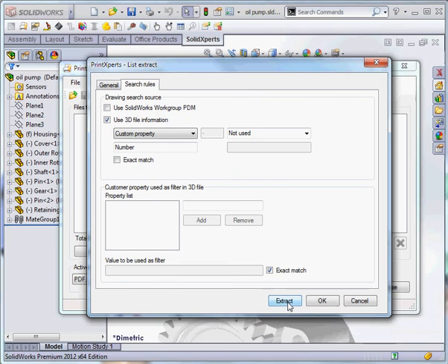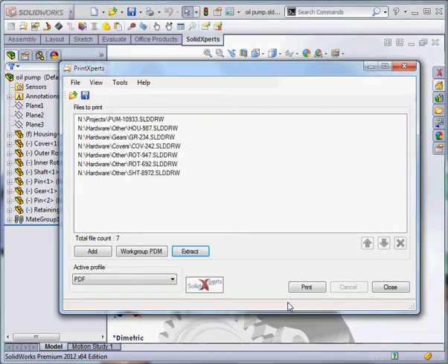You can also start the extraction from a drawing view or a bill of material. The difference is that it will be a little longer using a bill of material. The advantage is that the files will be printed in the same order as the rows in your bill of material. But if your bill of material of the top assembly contains a row for a sub-assembly, the drawing of this sub-assembly will be opened, so the bill of material of the sub-assembly is checked, and so on. So it may be a little longer, but as I said, the order is better.